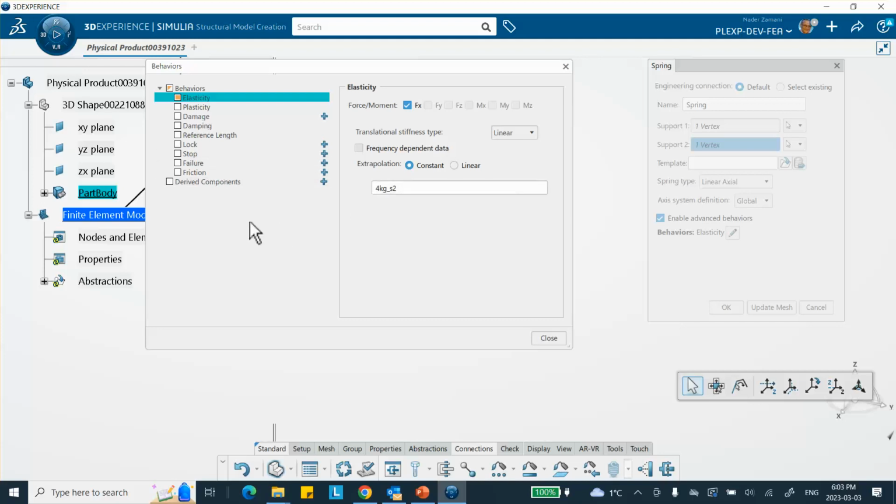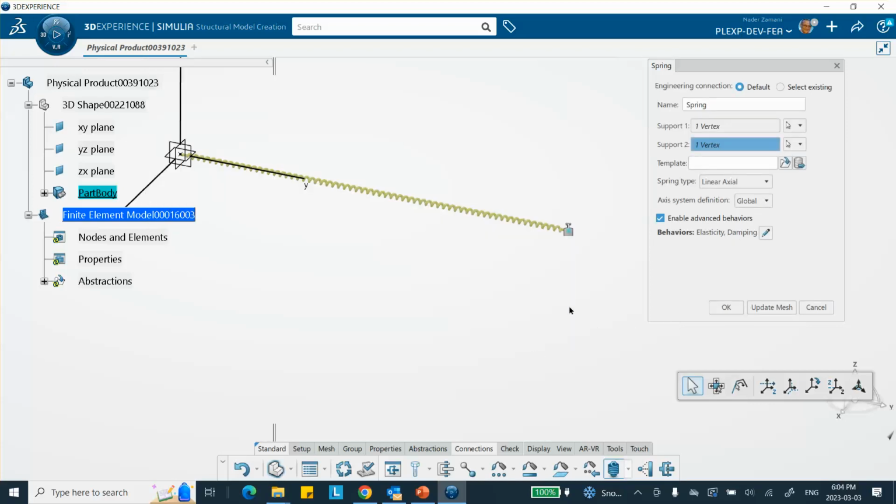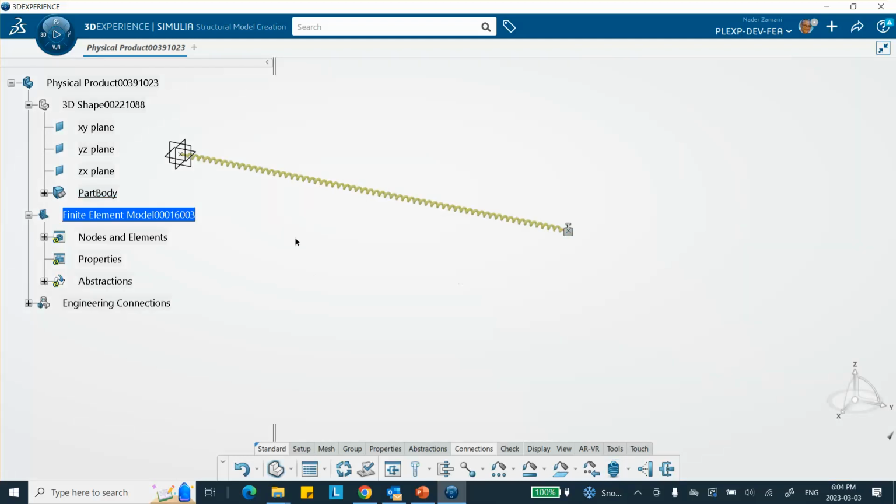Now to specify damping, ordinarily you have to go to this box here. You see that? Any of these white boxes, this damping box, but it doesn't work. You have to go to the text and do this. You go to the right of it a little bit, and now you select it, select FX. This is a viscous damping, and for the damper value, you put down 1, and we're good. This is actually our finite element model.